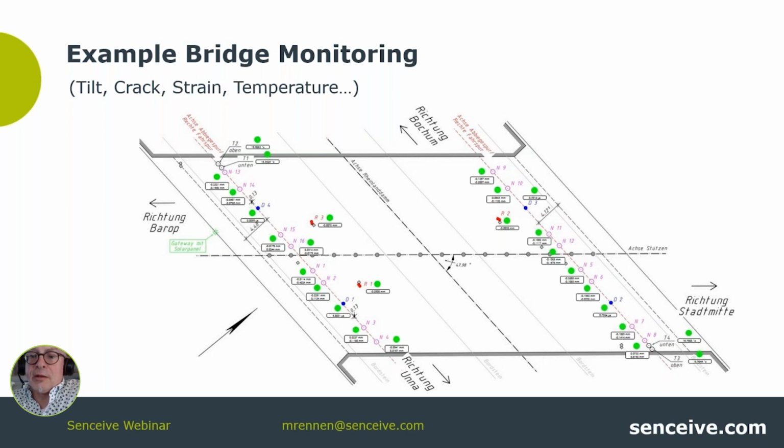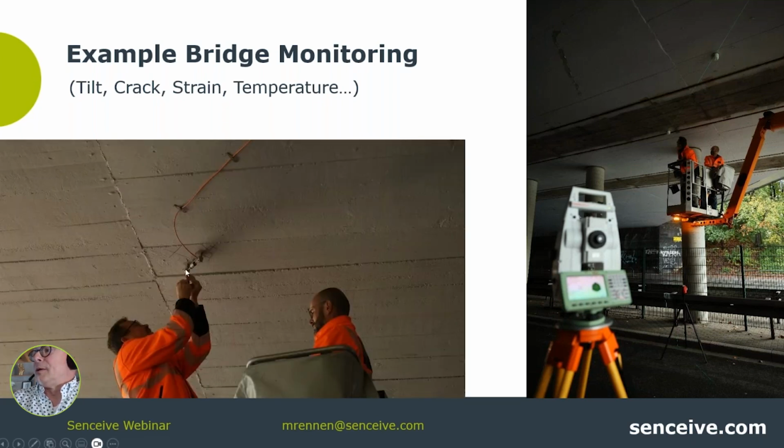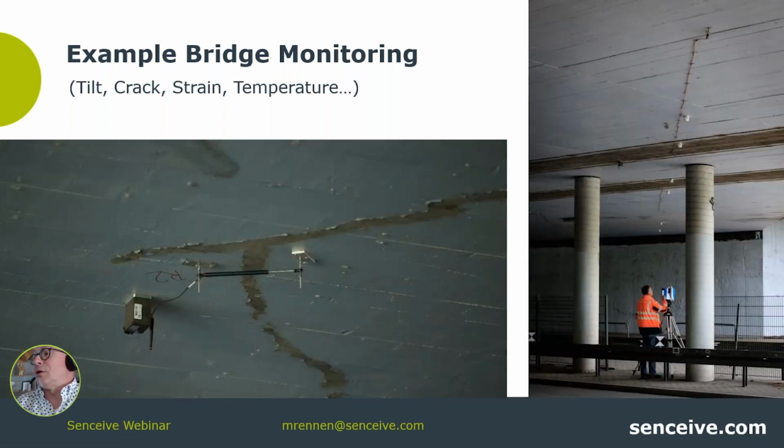The whole system then, we have pictures here, how the installation was done. Basically, the surveyors from the municipality of Dortmund, they did a stakeout of this pre-stressing cable that's lined in the bridge, and by laser, rotating laser, you see this light green stripe. All the sensors were exactly aligned onto this direction of the bridge. Here the installation of a strain gauge. And then, of course, where there were cracks, in addition, we had crack sensors, which you have already seen in the projects before.